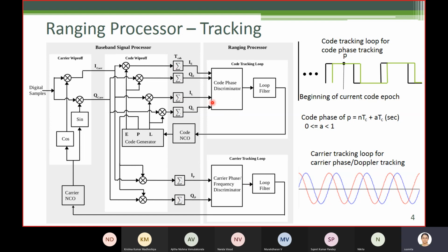Now, under some assumptions, this loop can be reduced to a block diagram representation with transfer functions. How does it look and when can we do that? We can make such transformation only when the discriminators operate within the linear region. The only nonlinearity here is in this part.